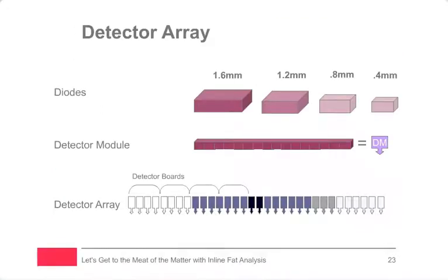These X-rays pass towards a detector by passing through the product. A detector is a range of different diodes which can come in various different sizes. They are assembled into a diode array, and they sit in between the tube and the product. So what does this look like in a system?